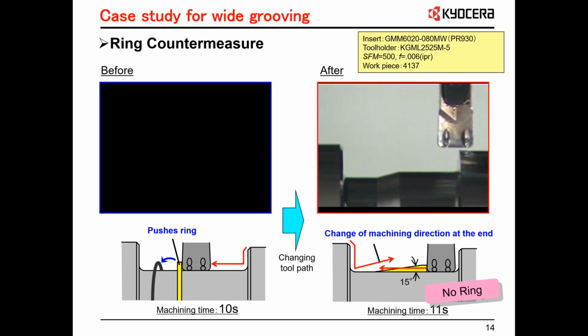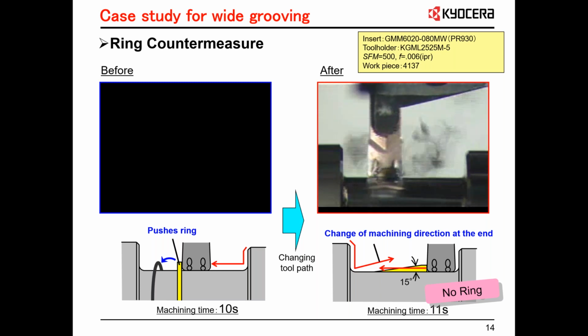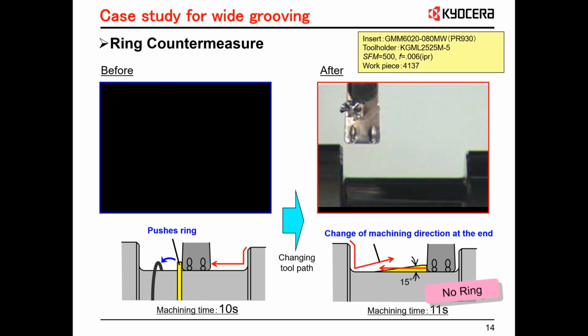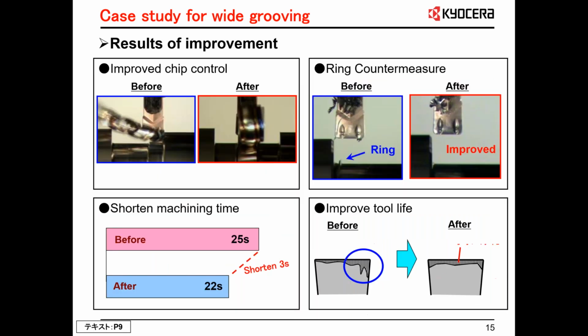So leave a slight angle. Now when we come in, as you can see, clear ring. We went from 4 plunges to 3 plunges. That meant we had to leave a little bit more on both sidewalls to finish up than with the 4th plunge, but that's okay. There was no need to get that. We can easily handle that much with the cut when we finally do the plunge on the sidewall.